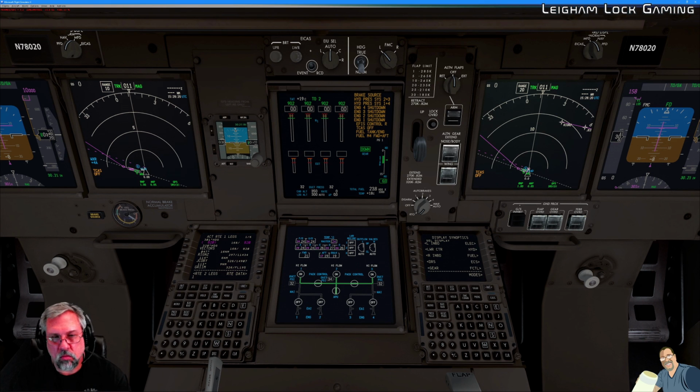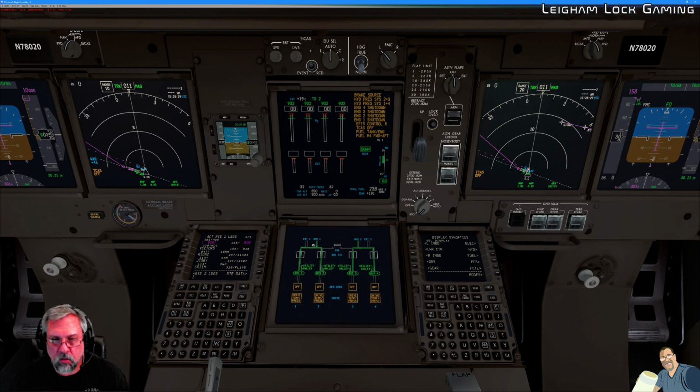From here, now that we've gone to aircraft power, we look at electric, right? We're no longer on external power, we're on APU1, APU2, and the bus tie has separated those two systems so that APU2 is providing bus 3 and 4, APU1 is providing bus 1 and 2. We can go ahead and request disconnect of the external power. Go back to the menu on our CDU, FS actions, ground connections. We'll go ahead and release ground power, and we're going to release the air conditioning unit. So they'll come and cart those away.